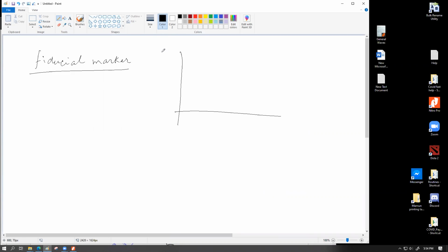The first thing I'm going to write is that if we draw the force-extension graph of a spring, we have a straight line part, which is the elastic behavior. Beyond the limit of proportionality, the graph starts to lose gradient. Up to this point, we have a uniform increase of extension with respect to force. Beyond it, the same amount of force does not give the same proportion of extension, which means the spring becomes easier to expand.